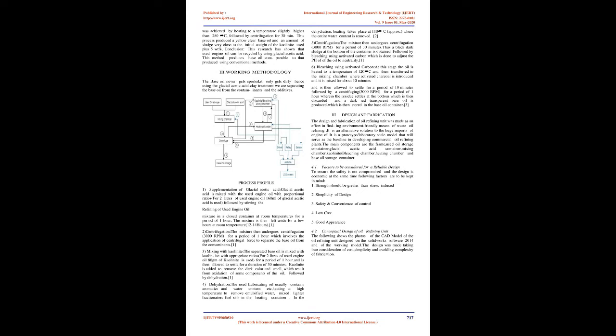2.2 Refining of used engine oil using bleaching agents. Mr. Abdul Qadir presents the result of regeneration of used engine oil using industrial bleaching earth and activated carbon as the bleaching agents. The used oil undergoes acidification and bleaching steps to remove the aromatic content and to improve the color and quality of the oil. The process showed a better quality of regenerated oil with a viscosity of 53.16 cP at 40 Celsius. The processes are as follows.